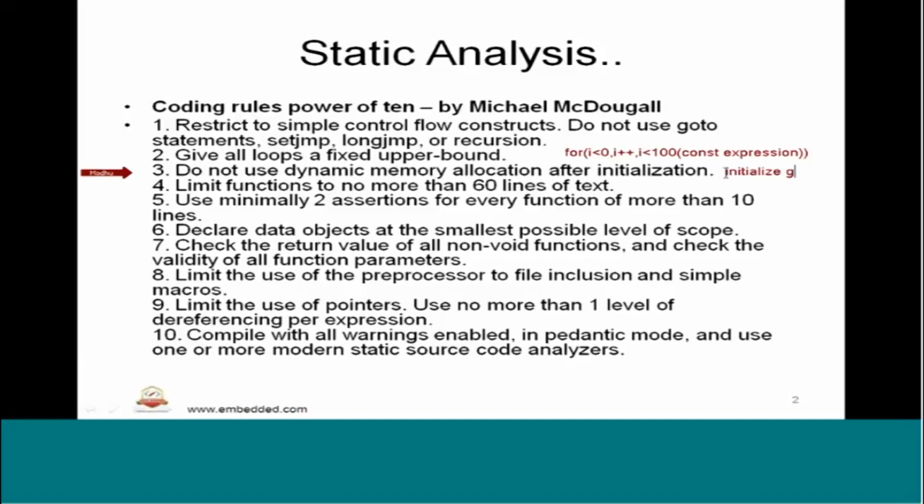Once we have initialized a variable or memory or any program flow constructs, we should not further work on the reinitialization of the memory, especially. That's what it talks about. So better avoid this kind of allocation, that is, how much memory is going to be taken during the program execution. You fix it in the initialization only and allocate accordingly. So do not use dynamic memory allocation.